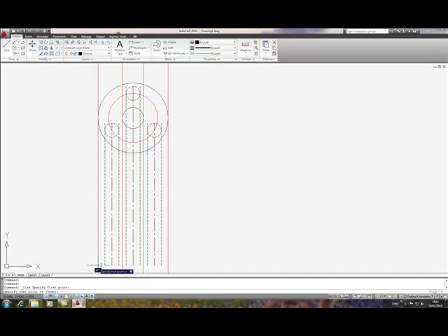and at the bottom here I'm going to draw a horizontal line between the two outer construction lines, 100, which is the diameter of this object, and then the height of the main body is 40, so we come up vertically 40 and left click, come back across to the left hand outer construction line and left click, and back to where we started from, which is down 40, and left click and enter.